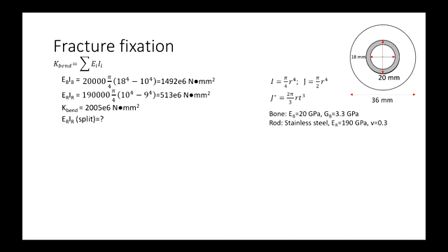For small deformation. If it was very large deformation, the split would open it up. But for small deformation, which all these beam bending calculations are based on, having a split doesn't actually change its bending stiffness. But for torsion, it changes things. So when you twist, that split allows it to give a lot more.